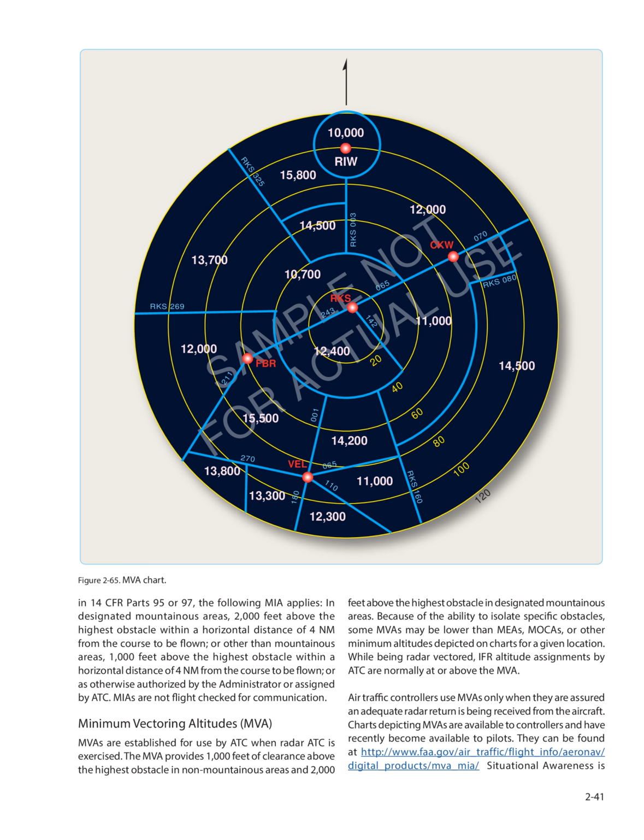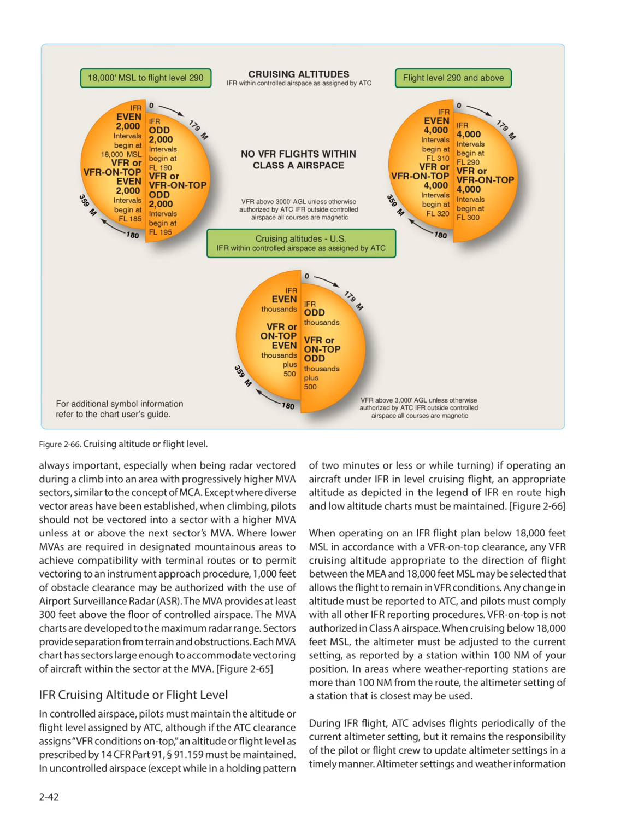http://www.faa.gov/air_traffic/flight_aeronav/digital_product/ma_mia/. Situational awareness is always important, especially when being radar vectored during a climb into an area with progressively higher MVA sectors, similar to the concept of MCA. Except where diverse vector areas have been established, when climbing, pilots should not be vectored into a sector with a higher MVA unless at or above the next sector's MVA.